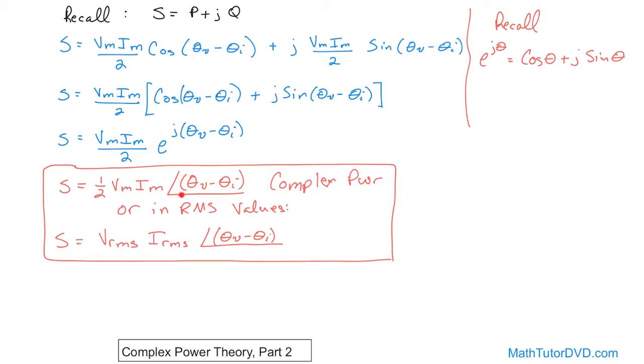You just subtract them, you make that a new phase angle, and then boom, you have a polar version of complex power. Hit the button in your calculator or manually translate it into rectangular form, and then you can immediately read P plus jQ, and you would know the reactive power just by reading it off. Just by formulating this new phasor and dumping it in, you can read P and jQ super simply, right?